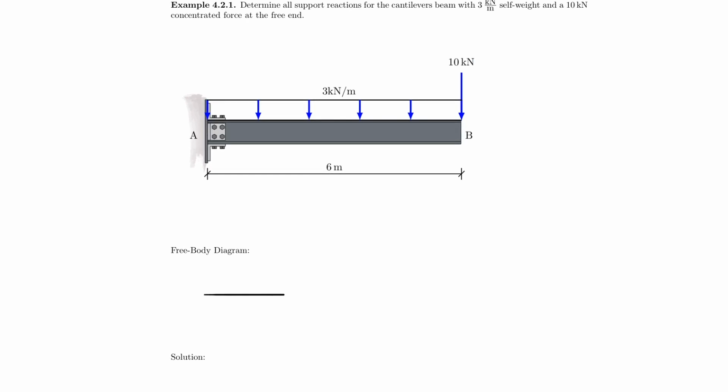So I will pull out my ruler here and draw this rigid body, and rigid body means that it has a dashed line underneath it, which then indicates the positive x and positive y axis. And what often students do is something incorrect that I will erase in a second, but they draw the free body diagram as such. That is not correct because it is not a force indication. You have to bring in the forces, and the forces that you have acting here are actually the vertical force, the horizontal force, and the rotation. So the forces would look something like that.